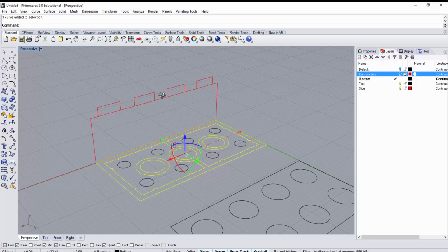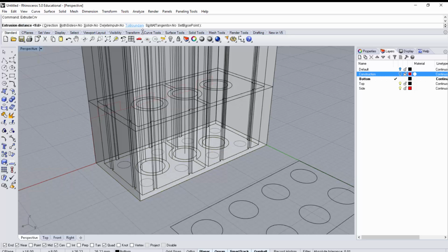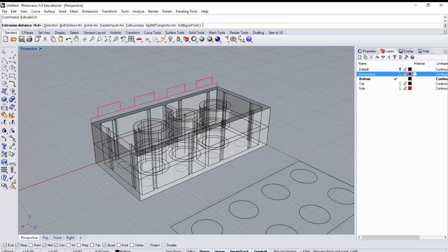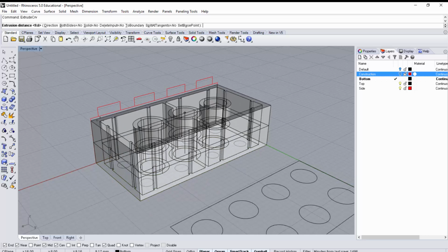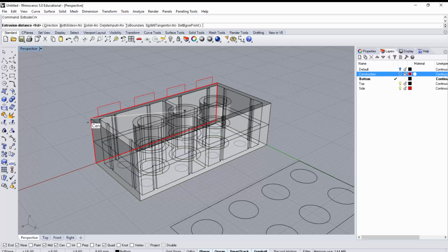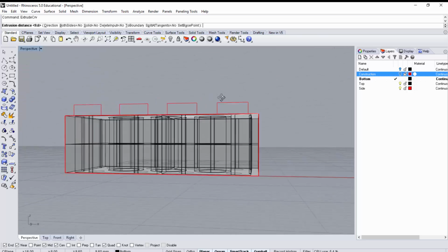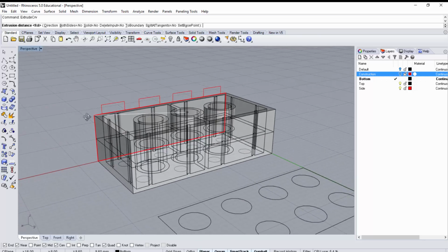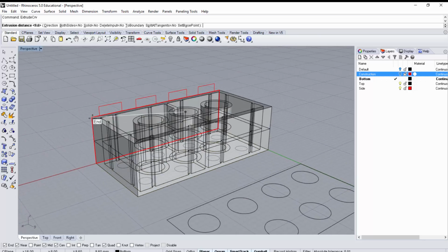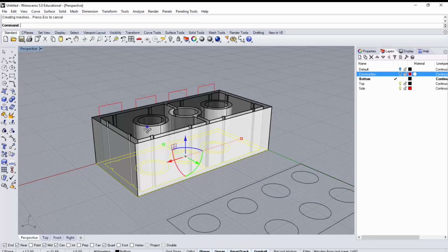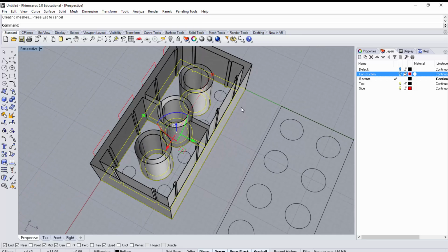So to do that, first you can type Extrude Curve, and you'll see it's extruding. And since I've got my side view here, or profile of the brick, I know precisely how high I need to bring it up. So we'll bring it there, got my O-snap on, click it, and snap it into place. Okay.